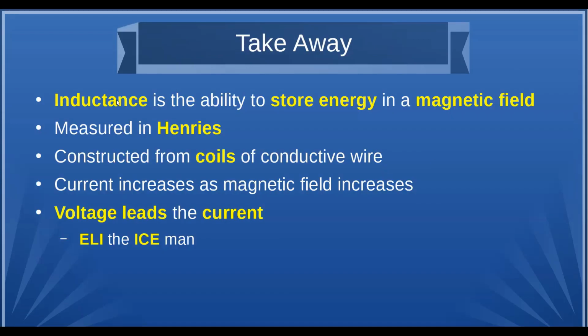So inductance is the ability to store energy in the magnetic field, measured in henries. We make inductors from coils of conductive wire. The current increases as the magnetic field increases, and the voltage leads the current, the old ELI the ICE man. That question is not on the technician test. It does come up on the general or extra.